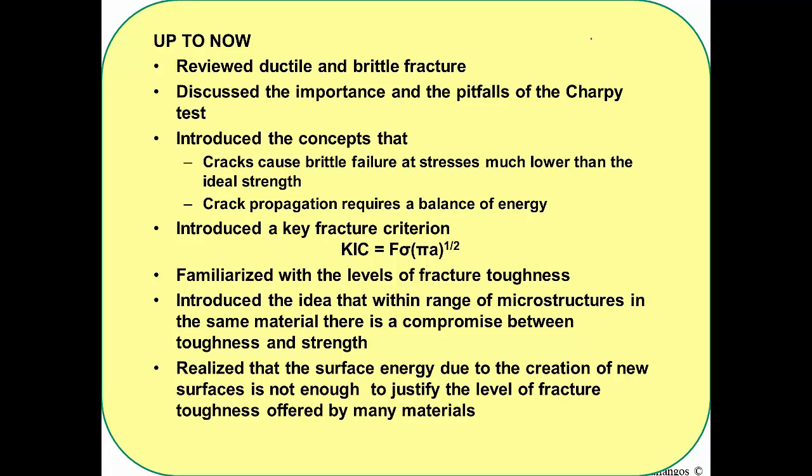And the last one, as I mentioned before, is that the surface energy due to the creation of new surfaces is not adequate to justify the level of fracture toughness that most materials show. We need to understand this because this difference hides behind it aspects of the material microstructure that can be utilized to design better materials with better fracture toughness.